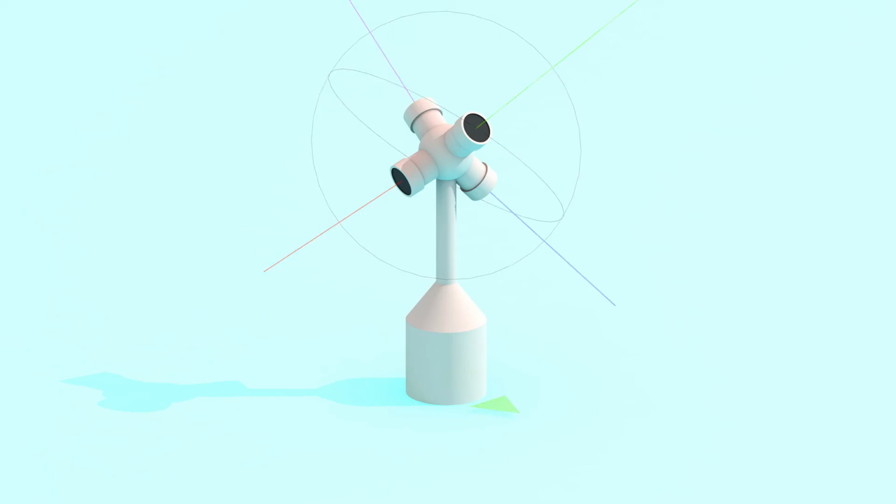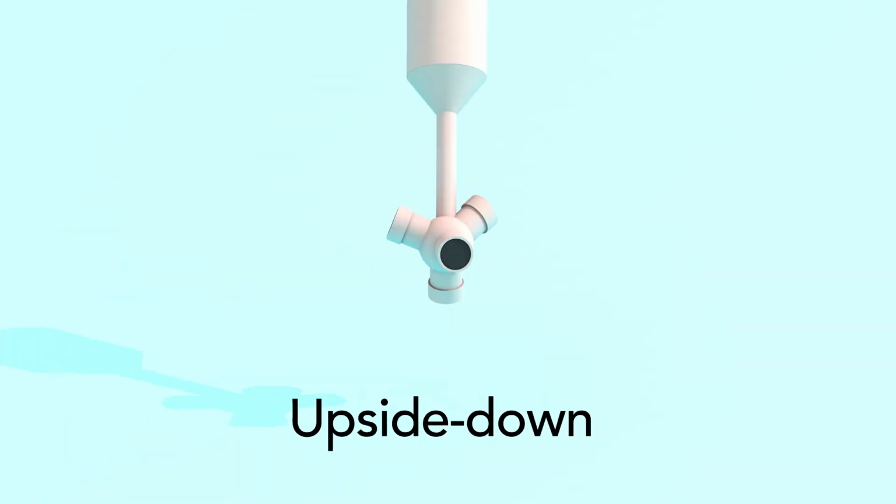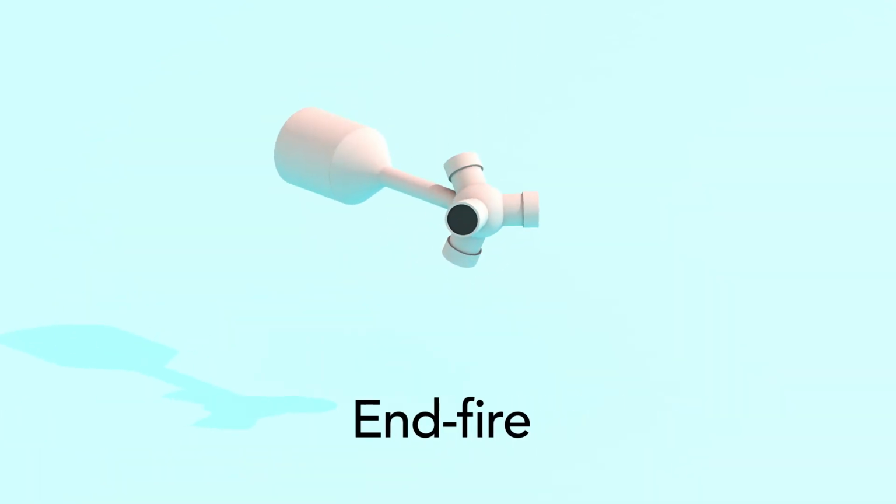Also, you're going to want to make sure and document the directionality of your microphone towards your sound source, especially if you're pairing that recording to a visual. Was your microphone front facing? Was it upside down, or was it end fire? All of these together later in post-production are going to help you accurately recreate the environment that the microphone was in. Even though it might seem like a lot to remember, keeping these 5 tips in mind when recording ambisonics will result in a better recording.